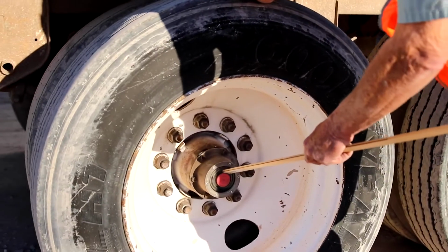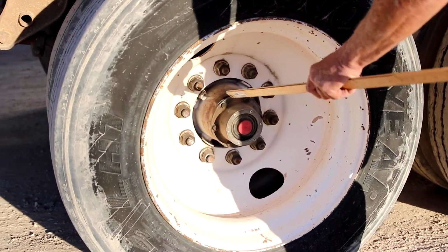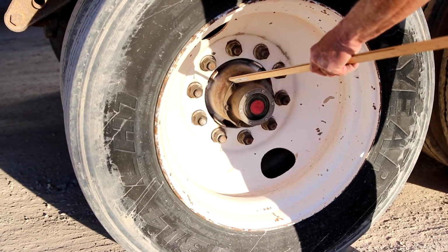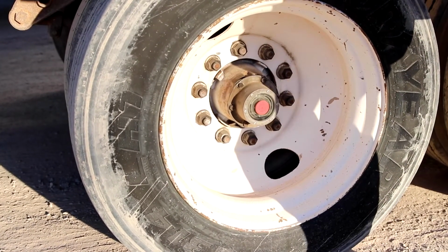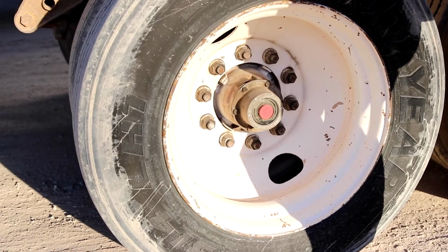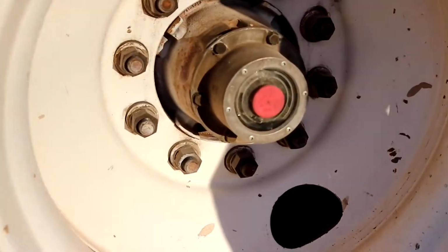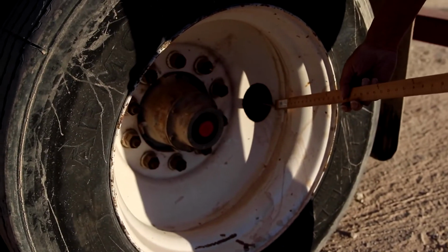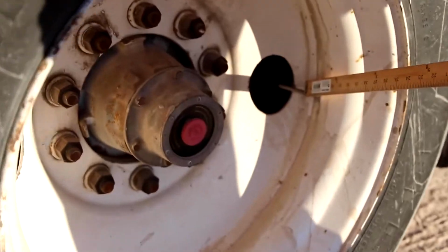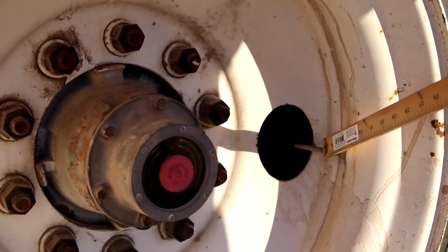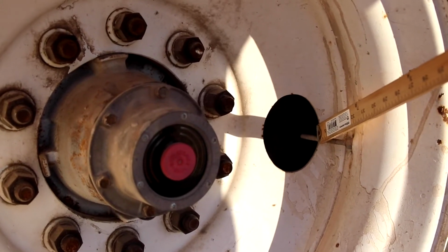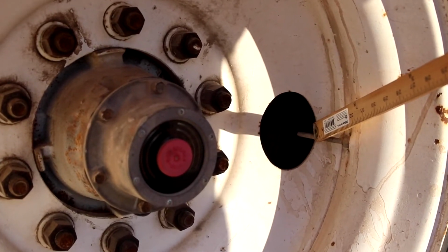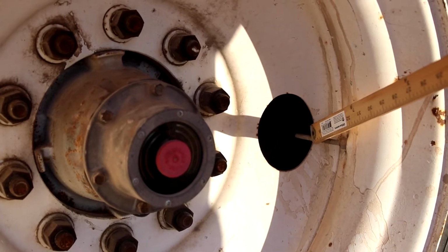And another hub seal. Mounted securely to the vehicle by nuts and bolts. This one has a window where you can see the oil level in it. It is not damaged or broken and not leaking. And this is my valve stem and cap, mounted securely to the rim. It is not damaged or broken and no audible leaks. And again, make sure that your tires are at least 100 pounds of air pressure cold.